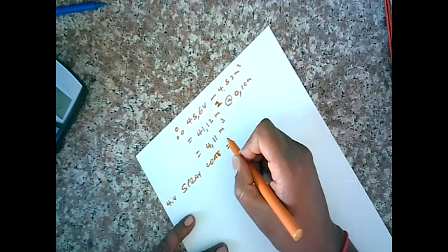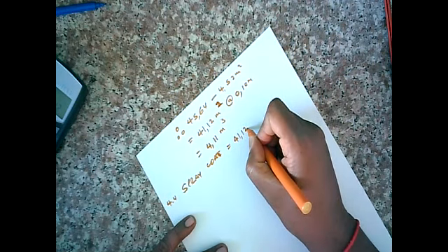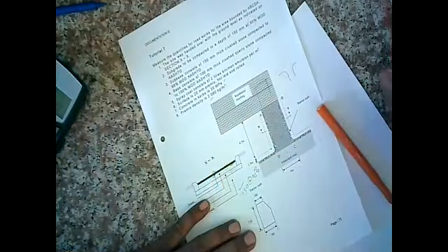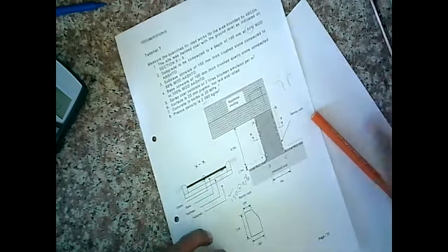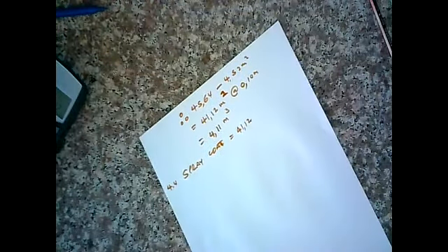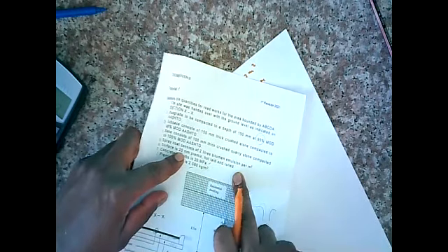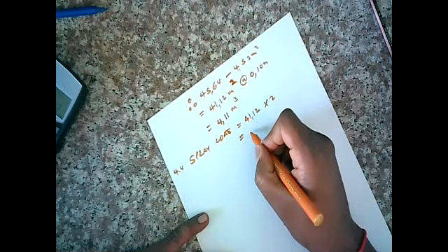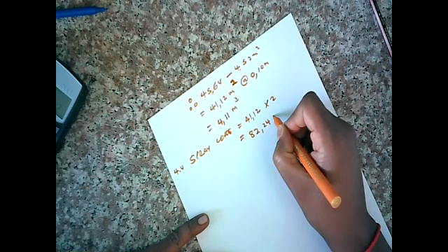You're saying 41.12 is the area. Spray coat. Remember, the spray coat is happening underneath this line here. Spray coat, basically your tack coat, right? And the condition says in your question, it's given as 2 liters per square meter times 2, and we're getting what? Let's see, 82.24 liters.